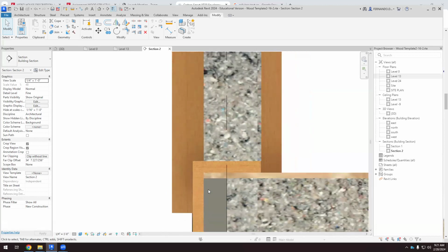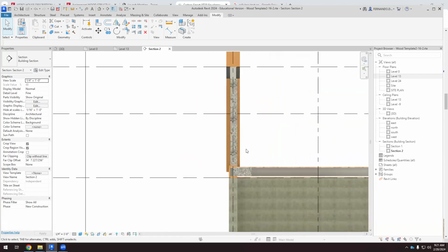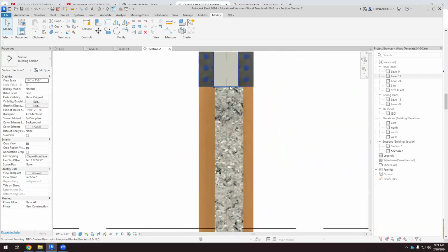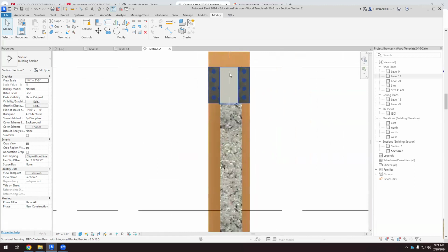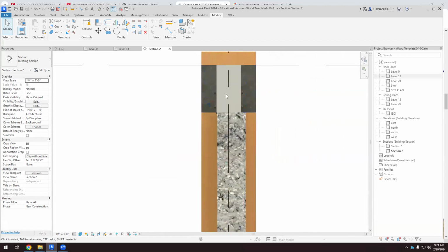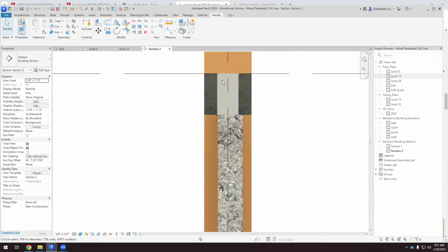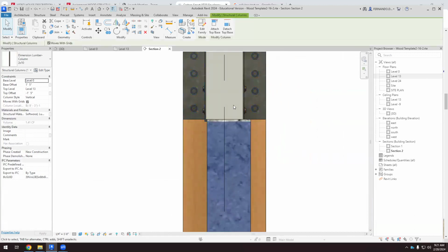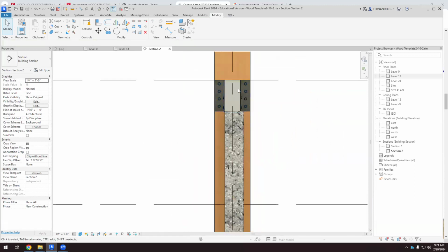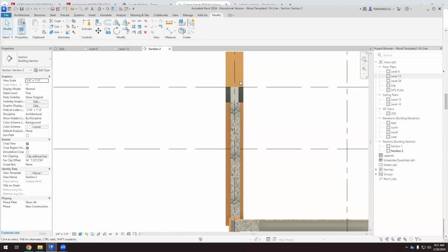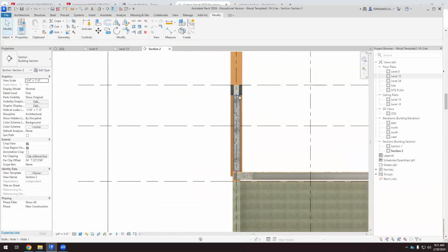But here we have cellulose. That's the rigid insulation. That's cellulose. I might have a small thermal breach here, so I have to fix it later. But we're on our way to do that. And here, if we don't do anything, there will be a thermal breach because of this beam, because we interrupt the cellulose here. Then when we're working with the second floor, we will have to do something.